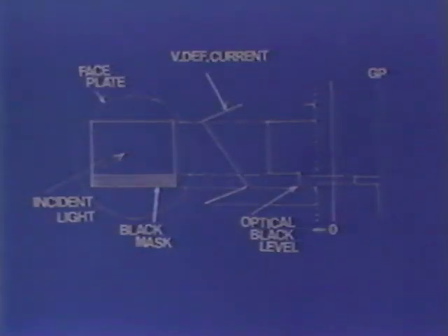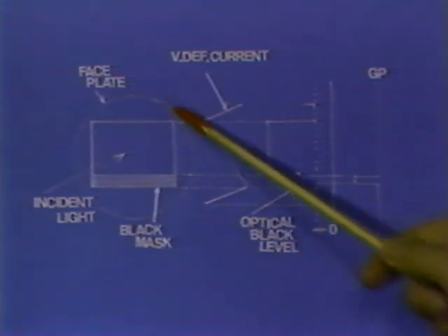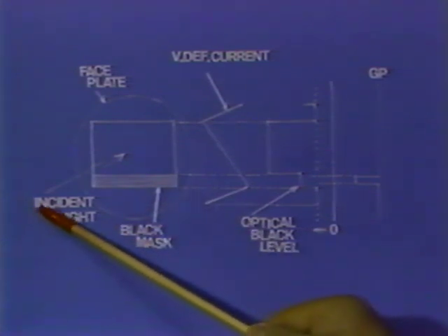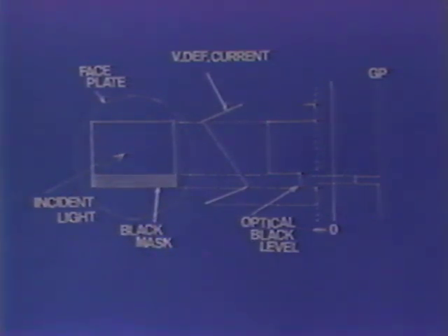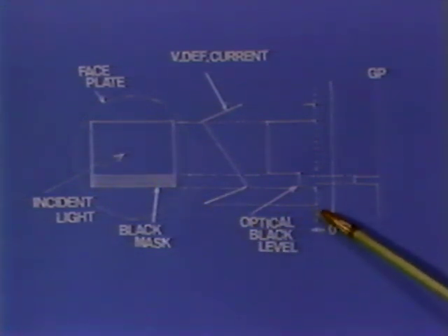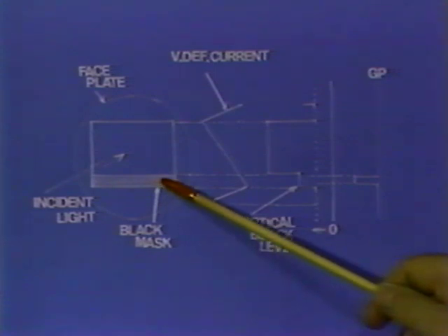The identification of the Vidicon's dark current is the first thing to do in the dark current compensation. How is the dark current actually identified? The Vidicon's faceplate is black masked, and the incident light rays are shut out by this part to make the optical black. The signal obtained by scanning this part is the dark current, and this is a level to be detected.